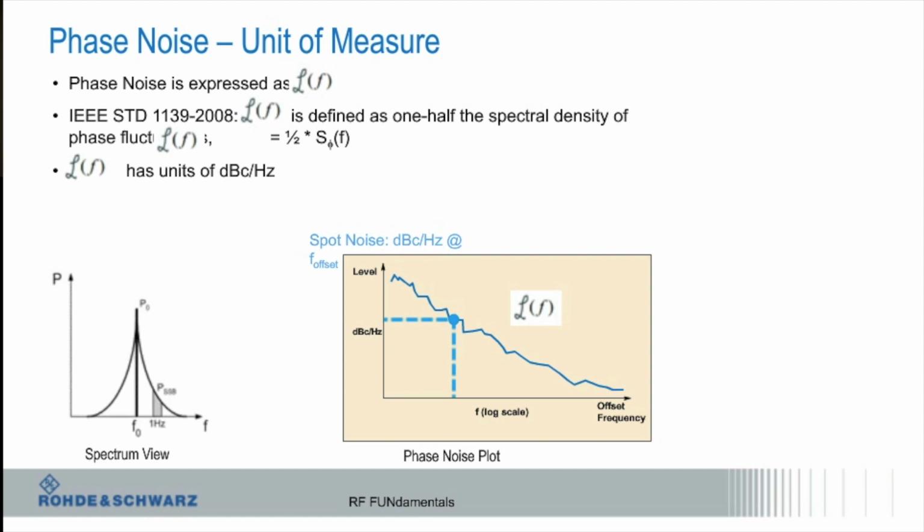I don't think I have this in this presentation. It's a conversation we could have another day. But the key thing is when I use a spectrum analyzer, forget about all the FFT stuff. Think about it as I have a signal, I'm going to mix it down, and then I'm going to give you an amplitude level. The tone that I use to mix it down with has phase noise on it too. So there are limitations in the spectrum analyzer itself in how well I can resolve that noise.